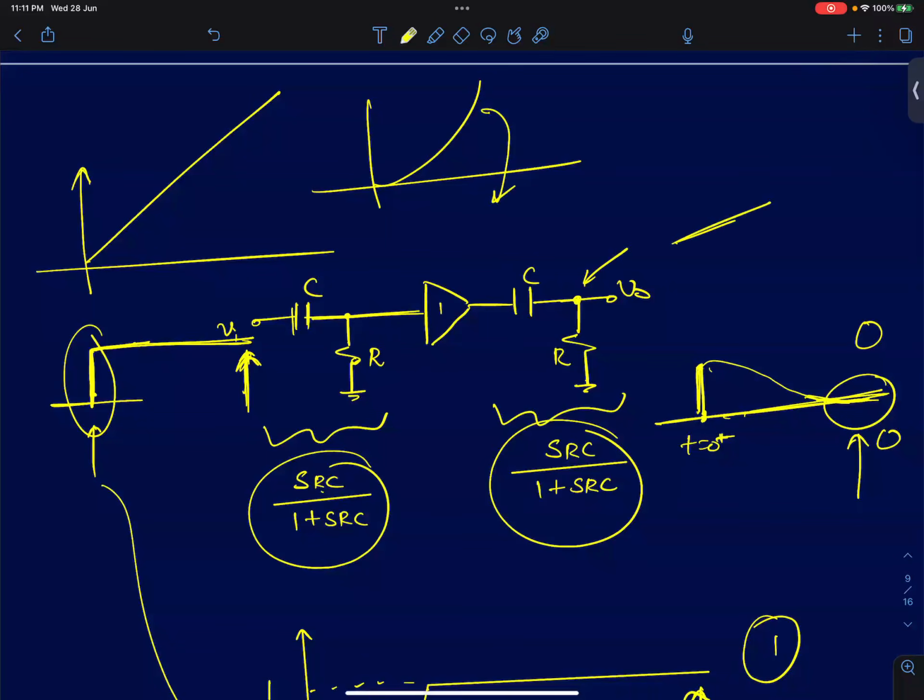So that's the power of what I discussed now. By looking at the frequency response, you can predict its shape, how it's going to look. Because it's going to behave like a second order differentiator in the steady state, if I feed a parabolic input, I should expect a constant output. Anything before that, whether it's a ramp or a step, if you differentiate it twice, it's going to be 0. So you should expect a 0 output in the steady state.